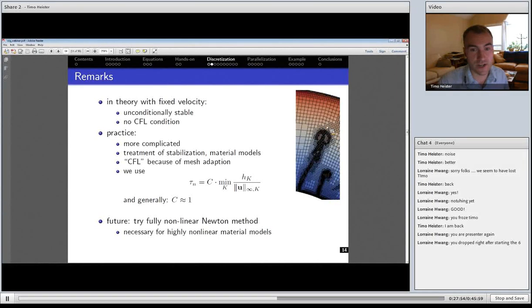If you look at the mesh on the right here, this is a plume rising. So imagine we make a large time step where this plume moves up further in this coarse area. Of course, it's not resolved anymore. So then the result would be really bad. The quality would be really bad. So we have kind of a restriction on how big a time step we can make so that we stay in the area where the mesh is refined. Otherwise we need to refine the mesh again and then do the computation again. So we have something like a CFL of 1. We can make a time step that is as big as the fastest velocity travels when going over one cell.